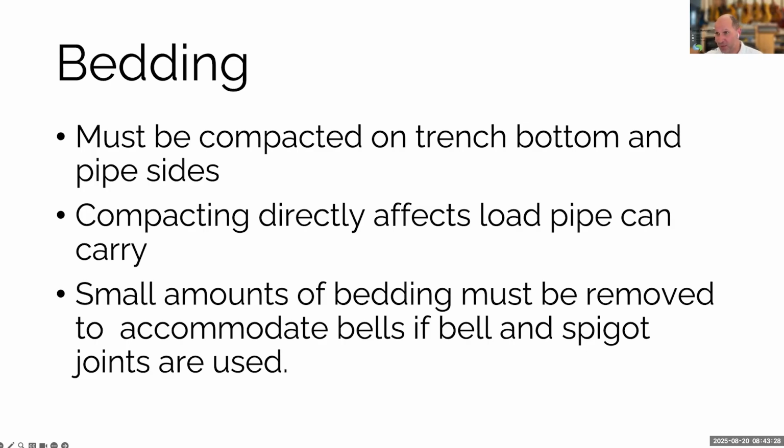That being said, it's important to remember that with HDPE pipe, where it's butt welded, it's all the same diameter, right? So you could effectively lay that in the bottom of the trench and you'd be good to go. But if you're using, for example, PVC or one of these cement pipes that have bells and spigots, the bell is actually bigger around than the rest of the body of the pipe. So you have to account for that.